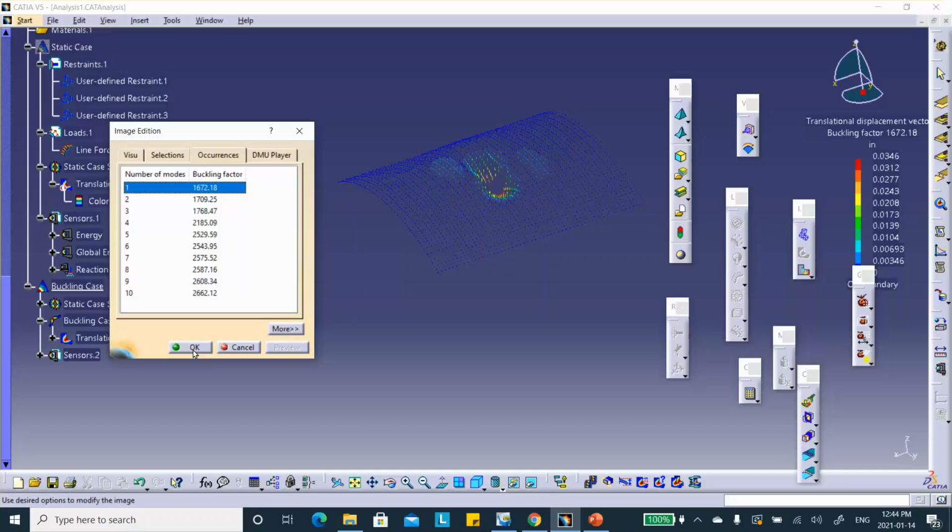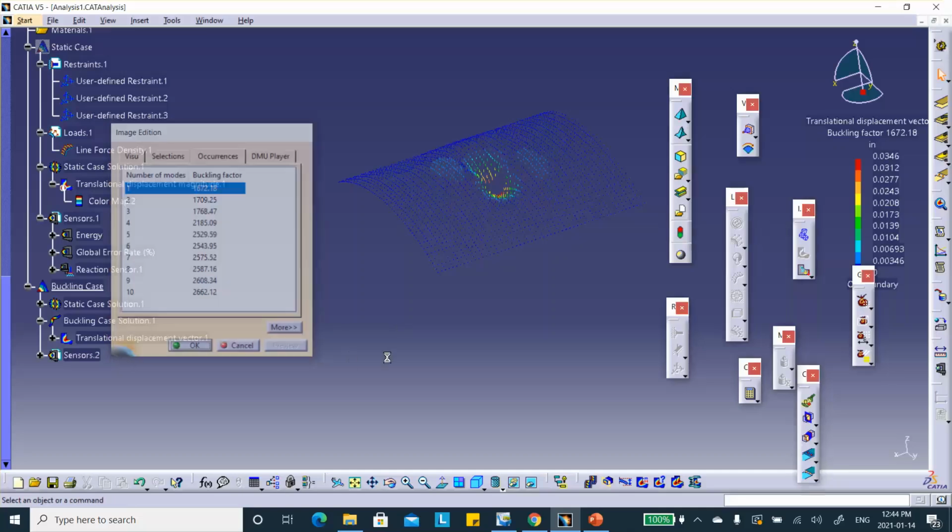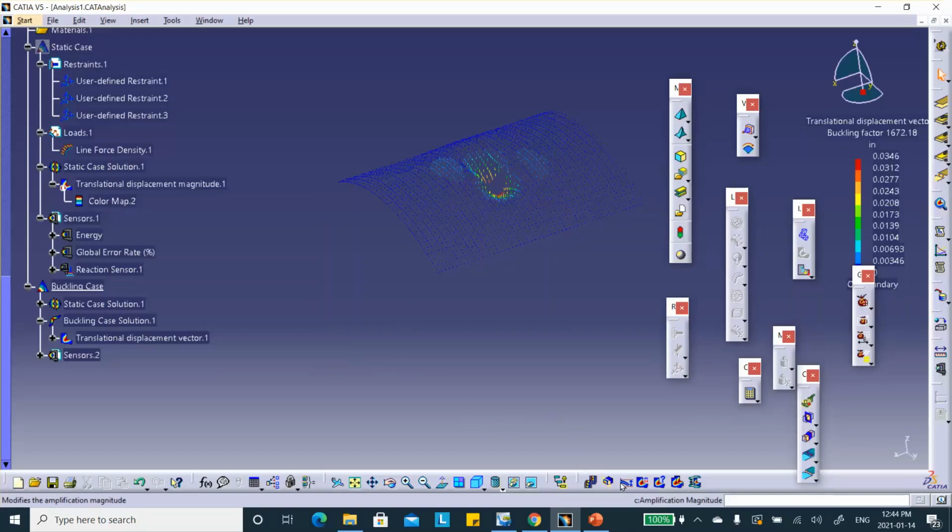All right. Good luck and have fun. I'm sorry for this screw up that I did. One of them was incorrectly putting the unit of 1 Newton per meter as the initial force that I applied. And the second is that my coordinate system was rotated so that everything had to be with respect to the user-defined coordinate system. I'm sure you're going to be okay.